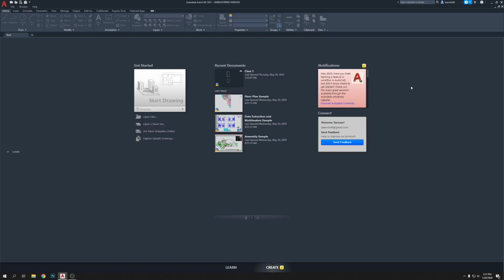Alright, so today in video 2, I'm going to open the file we saved last time, which was our first class. We set up our workspace and cursor size, show menu bar, bring toolbar, set up and lock toolbar, set up unit, text style, dimension style, views, and then we saved the file as a template. So every time we don't want to open the CAD file and set up everything we did in the first video. Every project we want to work on, we open the same file and Save As.